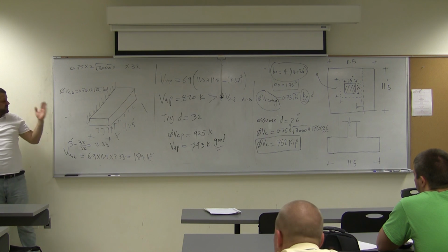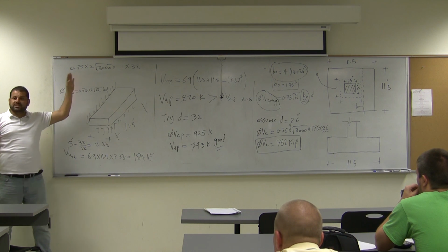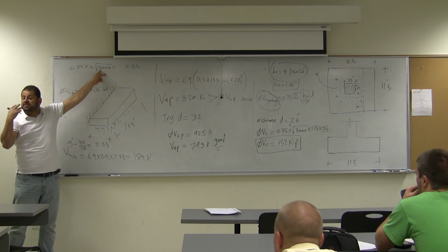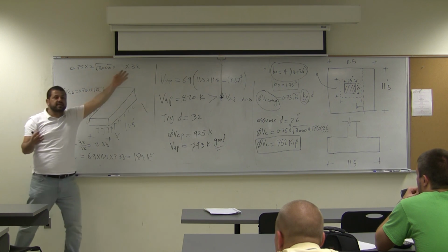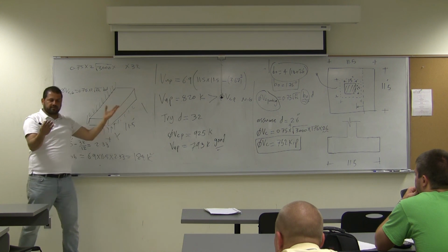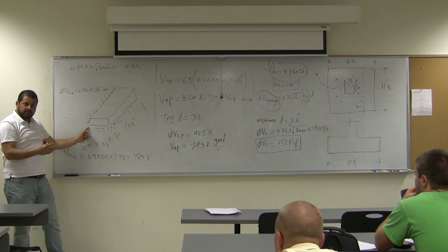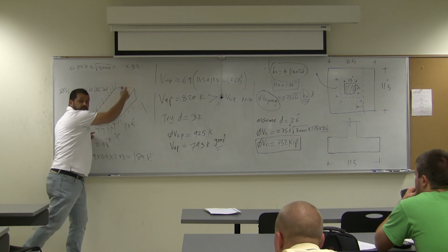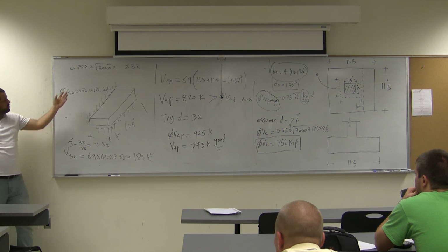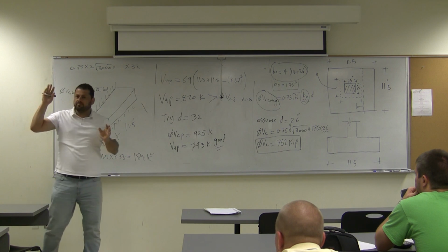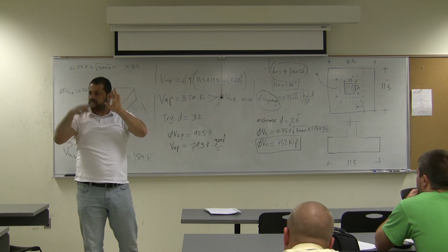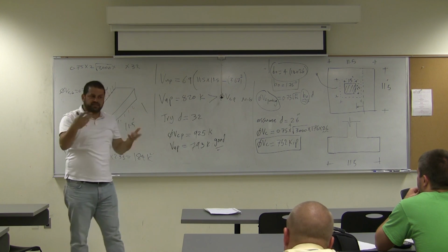You just think. What's that shear stress, you know what's this one here? 2 square root of f'c. That's the shear stress. BD is the area, the shear area. So what's the shear area? That's D and that's B. Right? So this equation, 2 square root of f'c times bd: 2 square root of f'c, that's the shear stress, times the area that the shear stress is acting on.